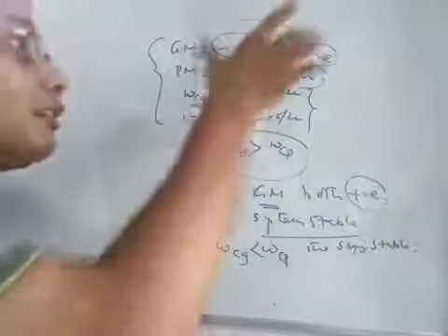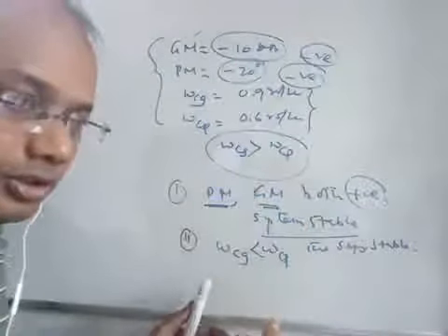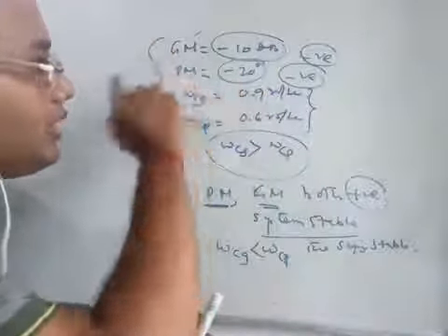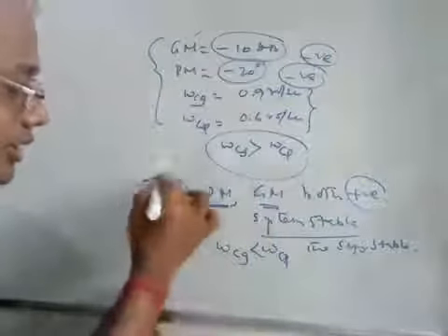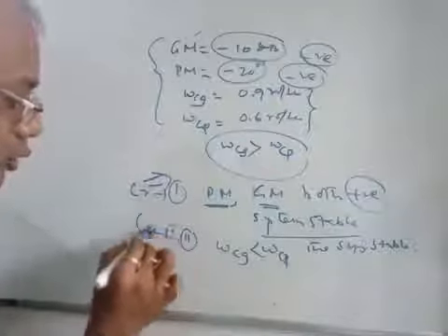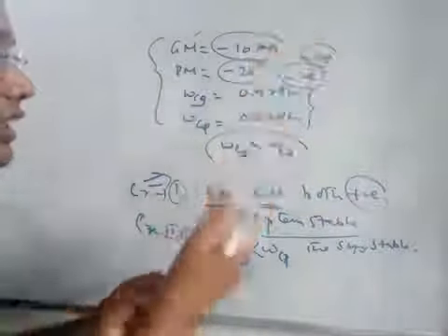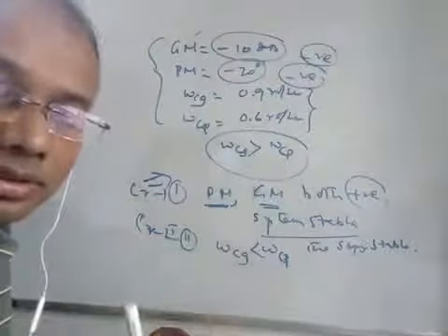Now coming to the graph we have drawn, given for any system. So for example, what do you obtain? This is negative and this is negative. So from this first criteria, this is criteria 1, and this is criteria 2. According to criteria 1, gain margin and phase margin both are negative. The system is unstable. No issue.